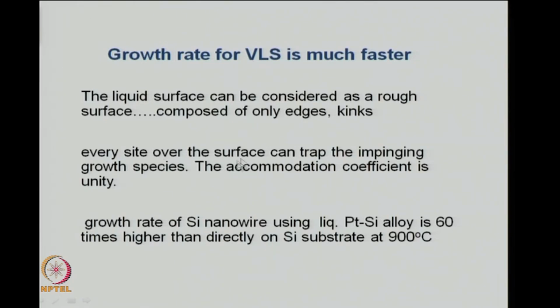Every site over the liquid surface can trap the impinging growth species, and so the accommodation coefficient is 100% or unity, and the growth rate can be very high. This is the reason that the growth rate for the vapor liquid solid method of growing silicon nanowires is much faster than other growth methods.